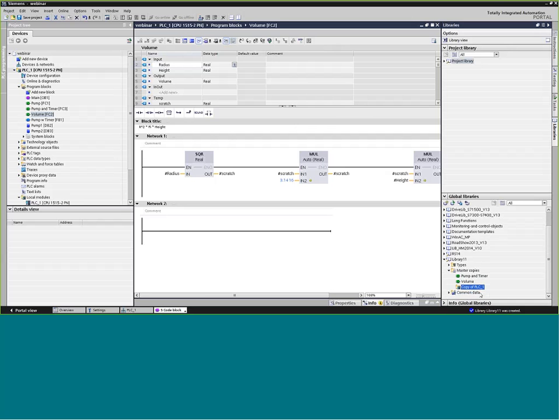But now I've got a copy of that PLC. So if this is a PLC that we're going to use for a lot of different applications in the future, I can start with a whole new project, pull this in out of my library and just drop it in, and we're reusing all the effort that we've put in so far today just to configure the hardware, the software, and anything else that we had done for that PLC configuration. Pretty powerful tool.